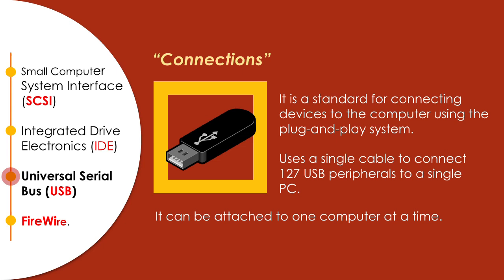Mouse and keyboard use the USB A type connector to be connected to a computer. The B style connector is designed for use on USB peripheral devices. The B socket is an upstream connector that is only used on peripheral devices, not on the computer.